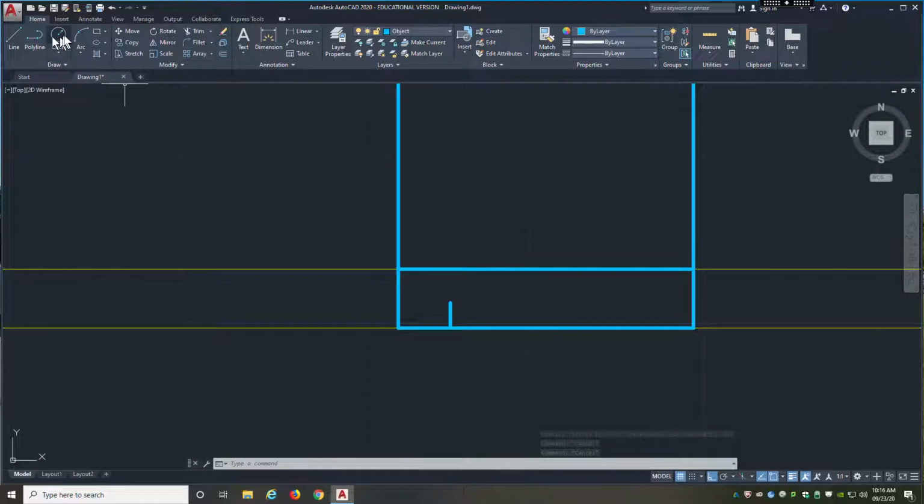So then the question becomes, let's put a circle in here. So I've got my circle tool, and my diameter is 1/4 inch. So I'm going to hit D, enter, 0.250. Excellent. Hit escape and offset tool again, and this time our distance is 2.750. And I'm going to offset that line that we created and basically do the same thing.